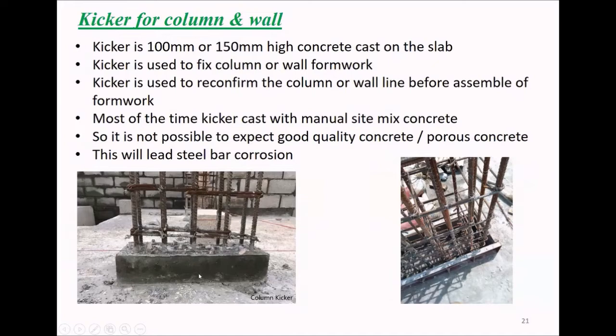this kicker casting time, this kicker concrete is very small quantity, right? You know, if you are going to use ready mix, we have to order minimum 1 meter cube. Sometimes all these kickers will be less than 1 meter cube. So what people do, people use hand mixed concrete, right? Most of the time kicker is cast with manual side mixed concrete.